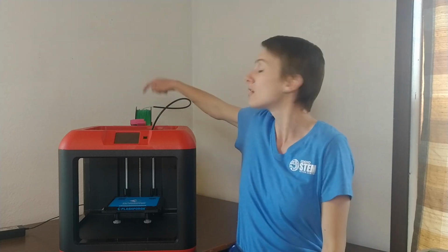One thing to keep in mind about STL files is that they only contain information about the surface geometry of an object, not color, texture, or any other attribute. So even though my model was purple in the example you just saw, the actual color of my print is going to be whatever color filament I load into my machine. In this case, green. The other thing to remember about STL files is that 3D printers can't actually print them, at least not directly. First, we need to convert them to another type of file known as G-code.